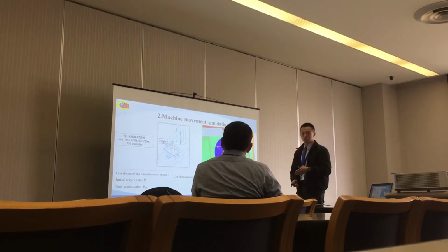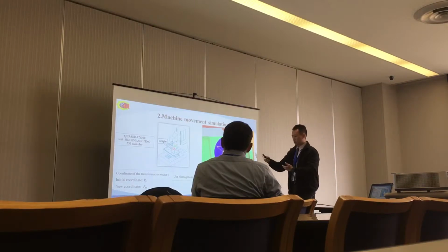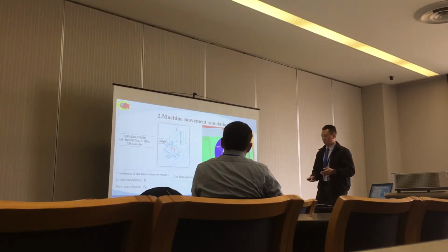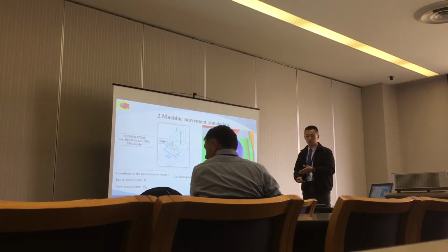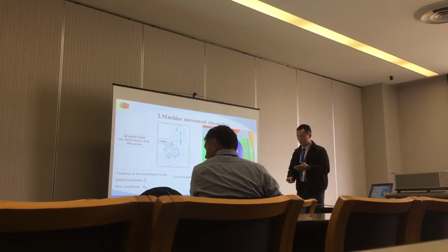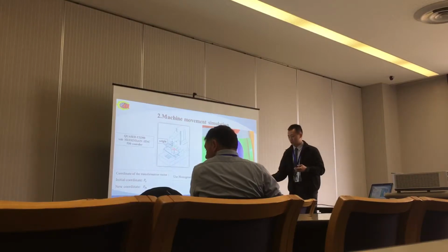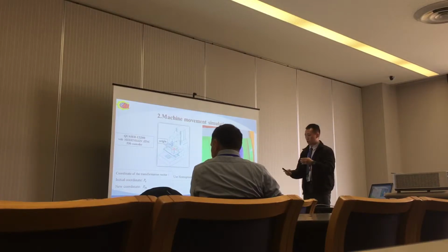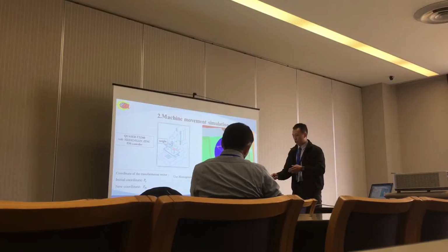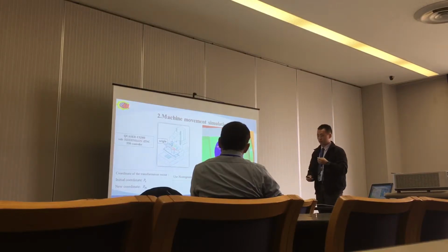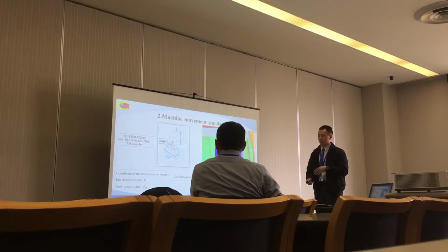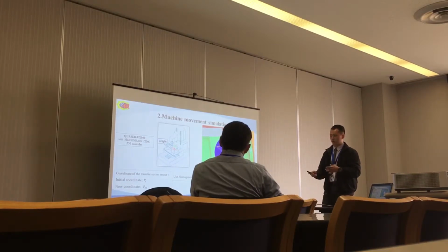But this definition will be changed after the incline platform command is executed, which is the A and C axis. That means it will rotate. So we don't want that. We want the whole moving position to move according to the mechanical coordinate system. So here's where we bring the homogeneous transformation matrix into the system. We have to use the homogeneous transformation matrix to convert the coordinates of the vector back into the mechanical coordinate system, so that the machine can move correctly in the simulation system.